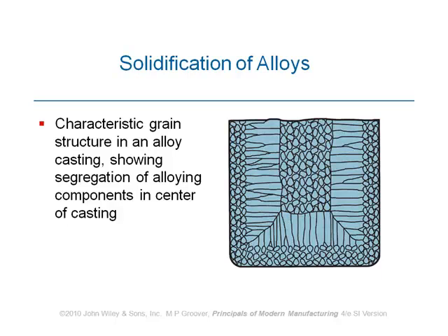Something between the two, right? Meaning that, do you recall the segregation which I explained in the casting process in a few lectures back? The segregation process, when we have got a grain which at the core is richer in one component, on the surface it is richer in the other. Remember that from lecture 2, I assume? Yeah? Actually those grains in here are segregated, meaning that in the core they are rich in one, on the surface they are rich in the other one.